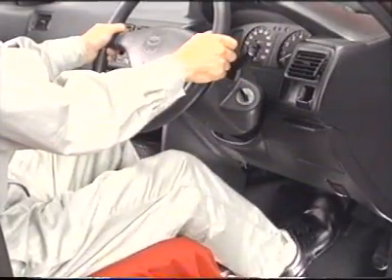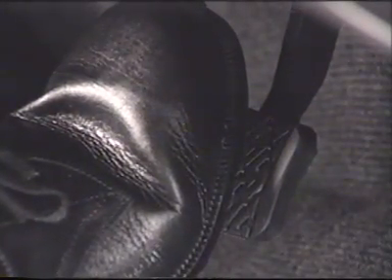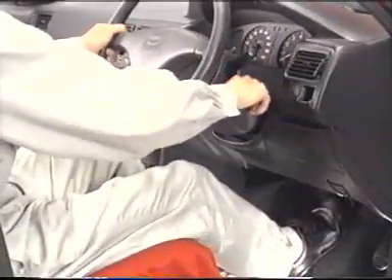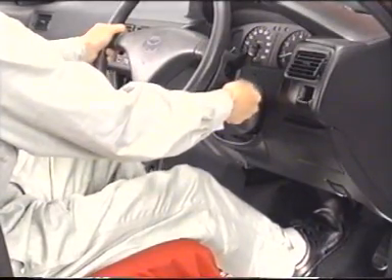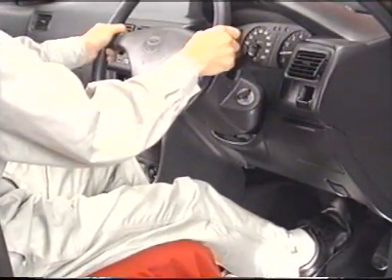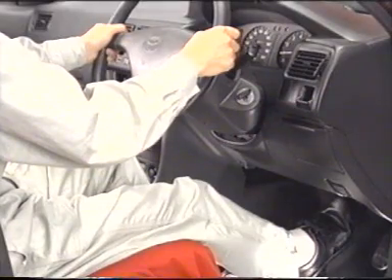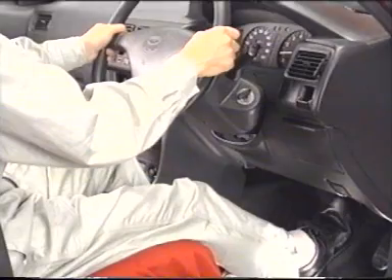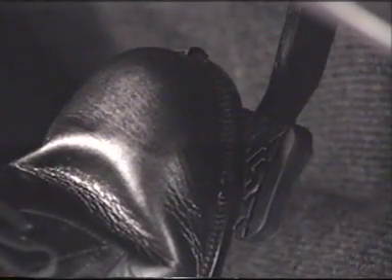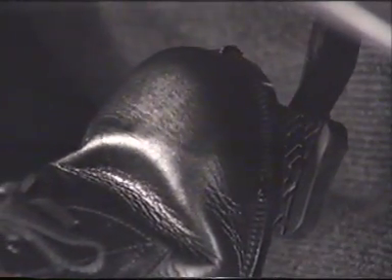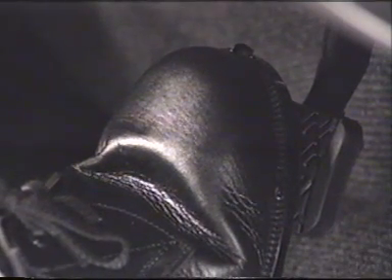Then check the operation. Stop the engine and depress the pedal several times until the pedal reserve distance becomes constant. Depress the brake pedal and start the engine. Check if the pedal goes down slightly. This indicates that a vacuum is produced by starting the engine and the brake booster is operating normally.